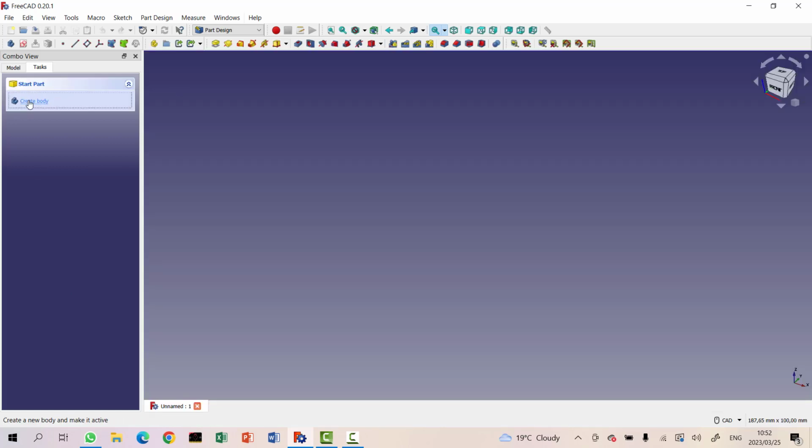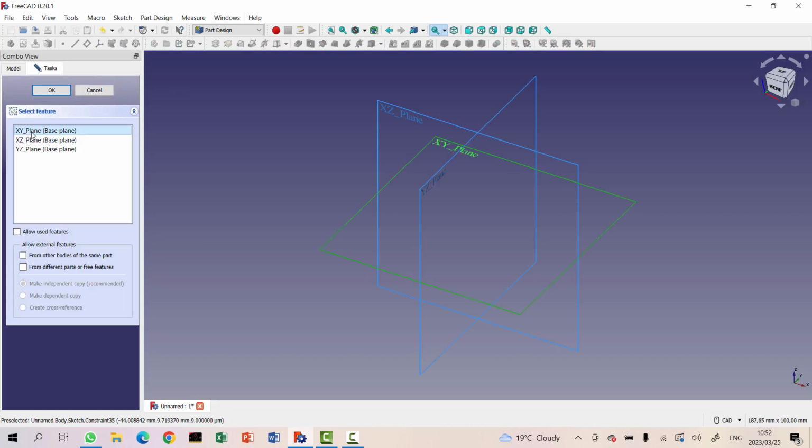Okay, in this video I'm going to show you how we made our panel guides. That's basically the little support thingies that we use to slide the panels, the side panels of the robot in, where the robot name and everything else is on. So let's see if we can do that. Control N for new project, create body, create sketch, XY plane.